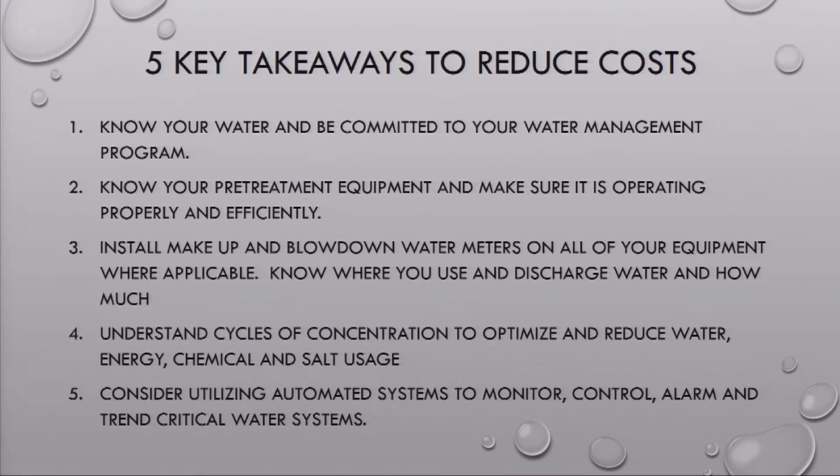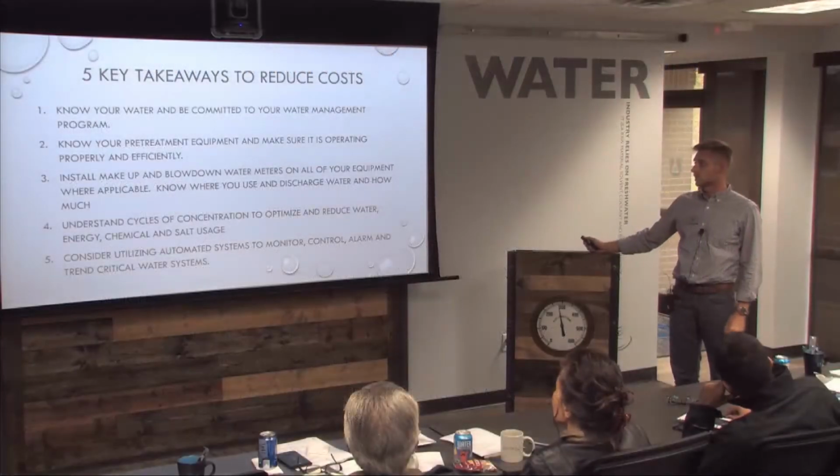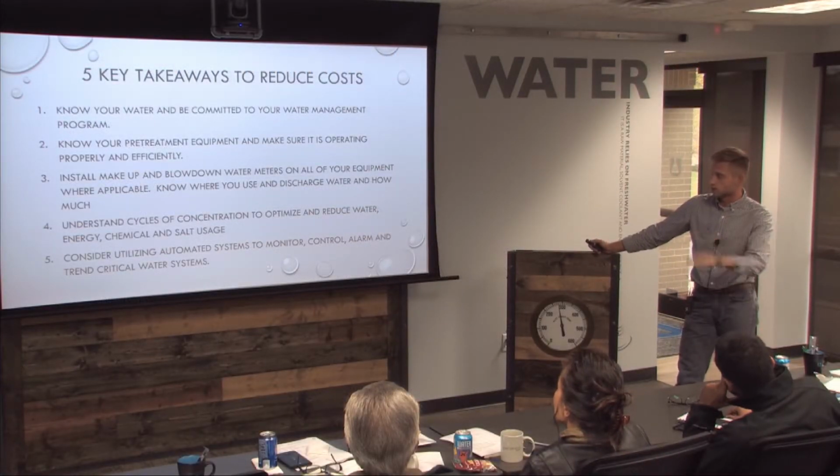Install makeup and blowdown meters. We like to meter everything. A lot of times we can catch things before they happen because of meters. Not to mention you can maybe get some evaporation credits. So we find meters important. Having an idea of how much water you're using versus going down the drain is extremely critical.